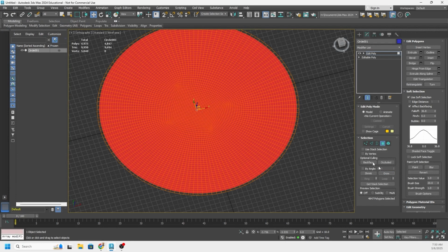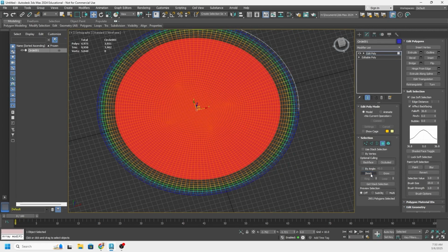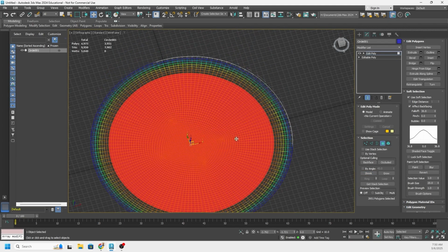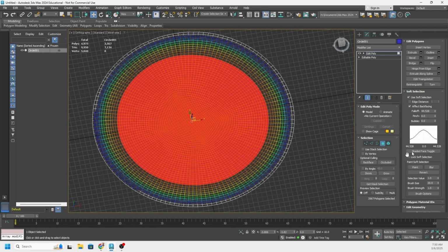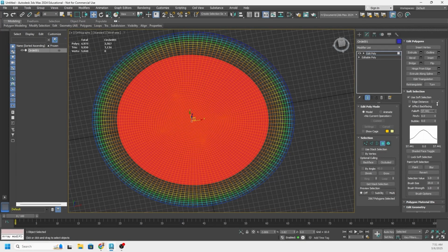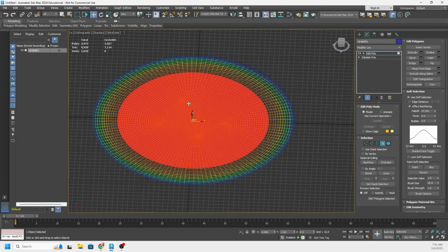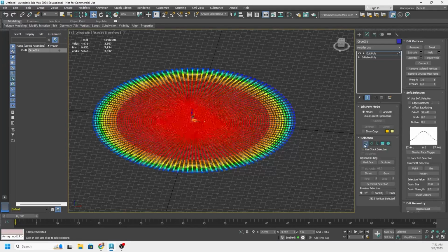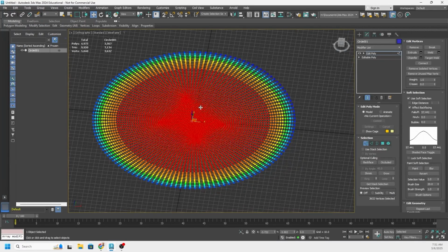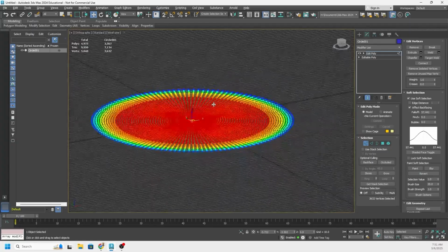It's a couple more clicks, and then thankfully just before that edge is selected I'm actually going to back it way out until I get blue around the edge here. So I'm going to increase my falloff and actually shrink this back just a little bit more. I'm just making a wider falloff range, and what that selection is going to allow me to do is, I'm going to hold control here, by the way, and convert my selection back to vertices. So holding control and selecting on the selection mode here, selecting a new icon, is going to convert my current selection to a different sub-object group.